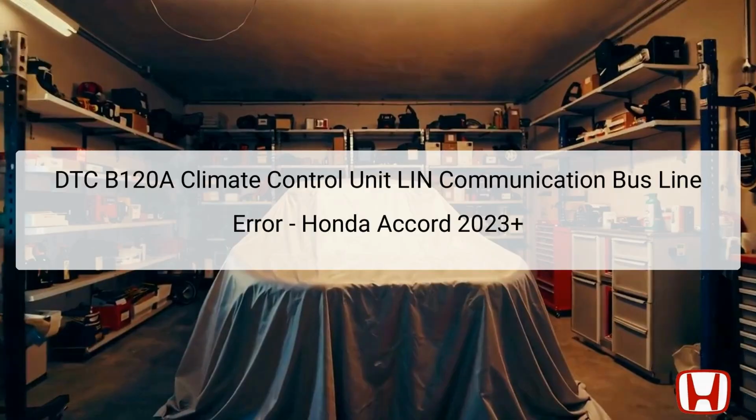DTC B120A indicates a climate control unit LIN communication bus line error in the Honda Accord models 2023 and newer. LIN stands for Local Interconnect Network, which is a low-cost, single-wire communication network.